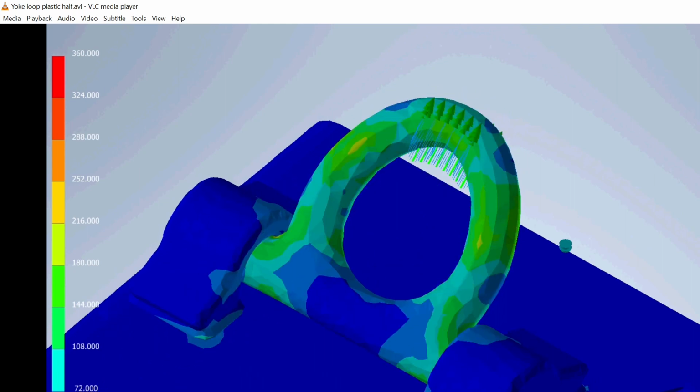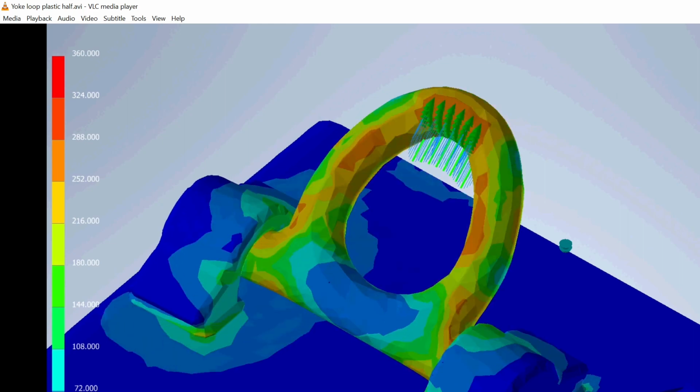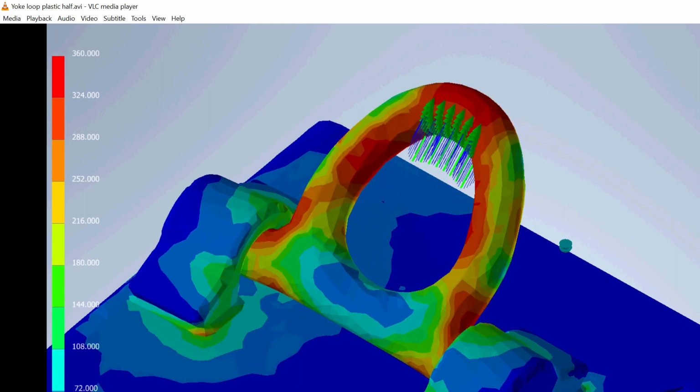But then that produces residual stresses. So if you have a different loading condition, you have to consider adding up these residual stresses from different loading directions if you're going to work in a plastic range. And also in plastic range, if anything is happening within the plastic range, that's a recipe for cyclic loading sensitivity.